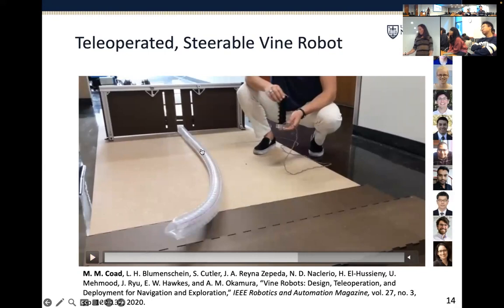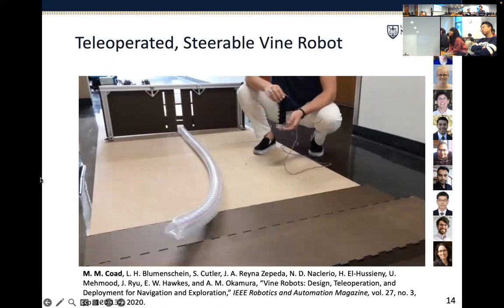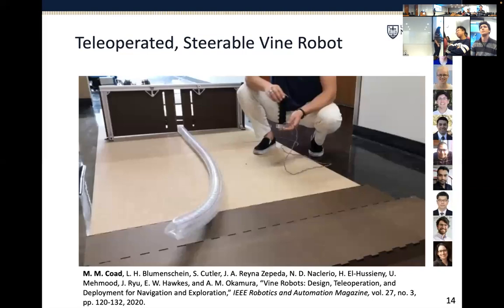And so it's kind of cool that even though we're commanding the entire body of the robot to bend, really mostly just the tip bends. That's because of the structure of the robot, where it's lighter weight to just move the tip than to move the whole thing. And part of this is held in place with some friction with the environment. Did that answer your question?